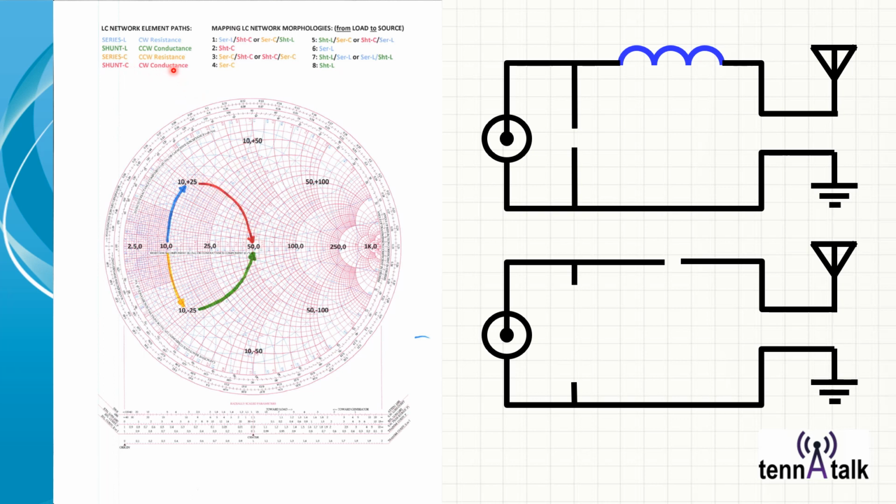And clockwise on a conductance circle means a shunt C. And there's my shunt capacitor across my 2 leads. And that'll get me to 50 ohms. The other way to get there is counterclockwise on a resistance circle with a series C, and then counterclockwise on a conductance circle. Counterclockwise on conductance is a shunt L. And those are 2 different ways to get there.